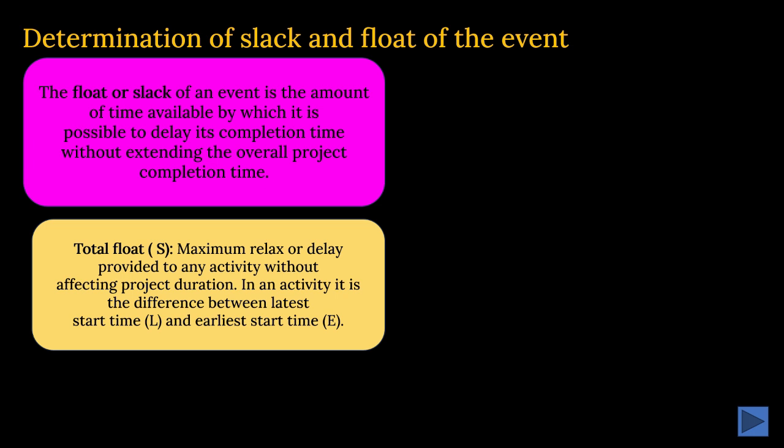We call it total float, which is denoted by S. What is the total float? Maximum relax or delay provided to any activity without affecting the project duration.